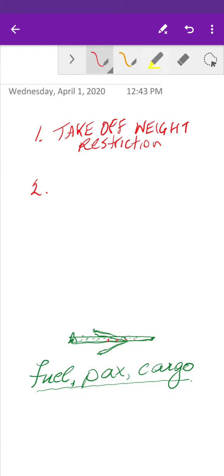What they've also factored in are side loads on the aircraft by crosswind. So yes, that's even part of the loading that this system has taken into consideration, and they've even considered the loads on the aircraft from going over a rough surface. So a rough surface can also add to the load on the undercarriage. And the other load that we've got, of course, is the load of our passengers, fuel and cargo.